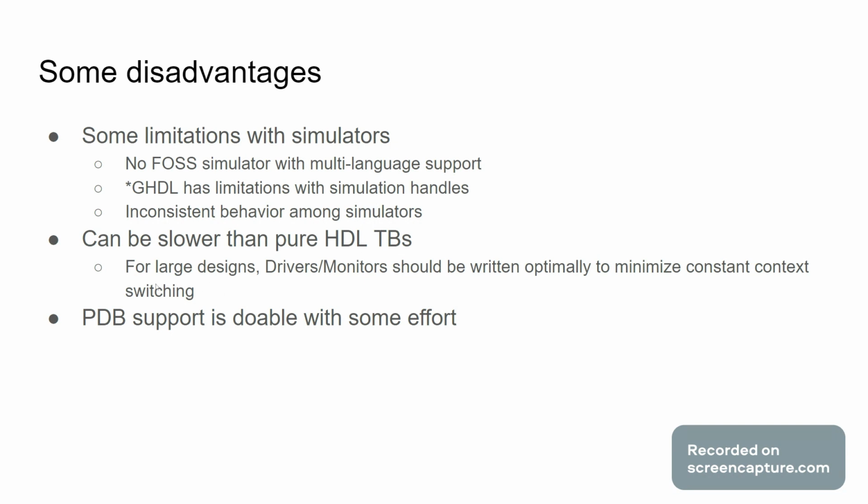At some point, I'll add an issue to my cocotb-introduction repo so I can do some tests and have some form of numbers. The one big thing, like I mentioned, is the clocks. I'd be curious to see how much benefit you get from moving the clock out of Python and into the HDL.